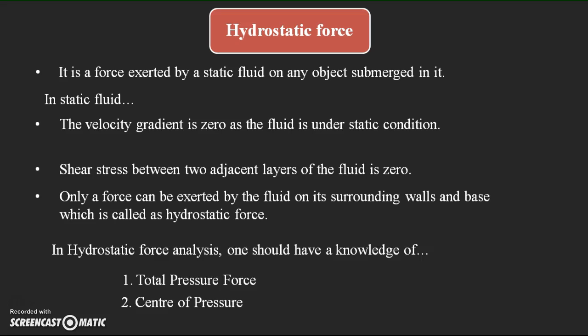Basically, pressure is a surface force, and we have to know what total force is acting. Whenever we consider a liquid, the pressure increases from the free surface to the bottom surface. So we have to know where the maximum force is acting; that is related to the total force. And where it is acting is the center of pressure, which is related to the point where the total pressure acts.